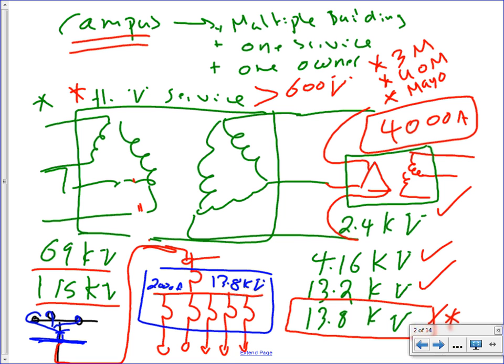For example, if you have overhead service, they bring the voltage drop power all the way to the service head, and from there you bring your service conductor and they tie it together right at the overhead. That's the point where they tie in. That's a demarcation point. If you're coming from underground, typically you pull your conductor from the meter all the way to the pole, and the demarcation point will be right at the pole where you tie your conductors to their transformer on the pole.